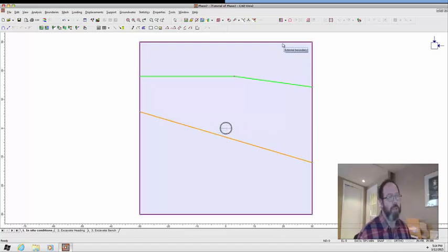Out near the boundary, the stresses should be fairly uniform and more like the in situ stresses, so they can be much coarser. If you had a problem where you were going to apply a foundation load, for example, to the top of the model, then that's another area where you might want to have some refined mesh.